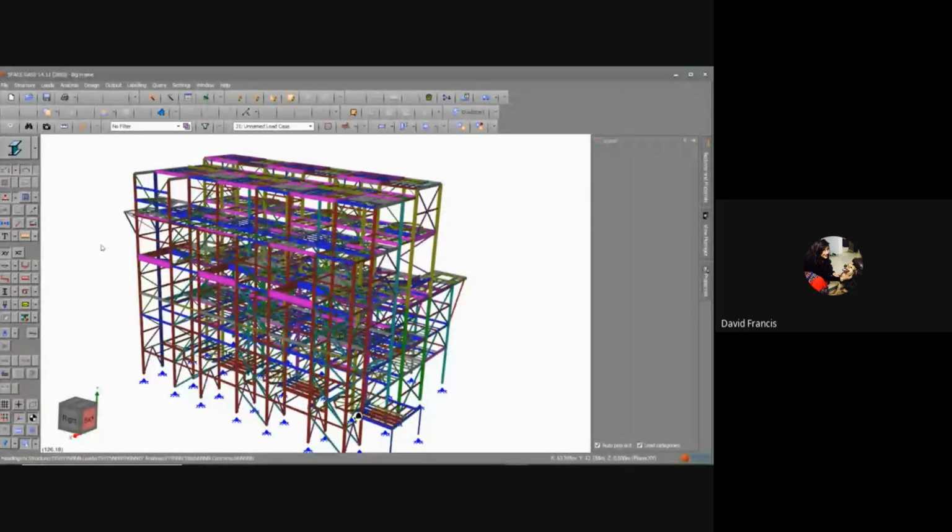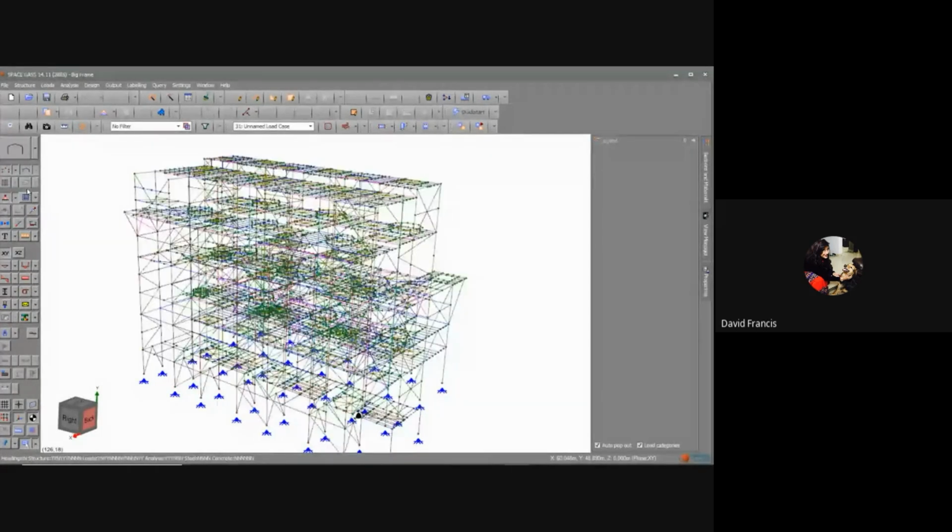In terms of getting the overall menus, on the left-hand side, these are mostly settings that you turn on and off, and they can be done at any time during some other sequence. So you might be busy adding loads on the right-hand side in the main screen, and then you need to turn something on that's off. You can come across to the left-hand side and select an icon. For example, I can select this option, and I then have 3 choices, and at the moment we're showing fully rendered mode. I can go to the wireframe mode.